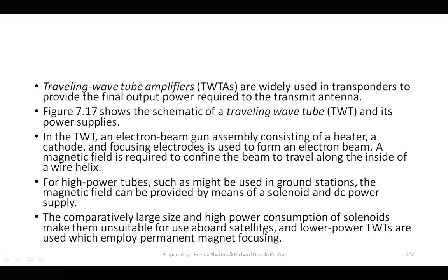The batteries available on the satellite will have to sustain during the eclipse. If I try to have these high power consuming circuits, then during eclipse, as you know, some eclipses can last up to 72 to 75 minutes. Don't you think these high power consuming circuits will drain the battery, and we will lose contact with our satellite?